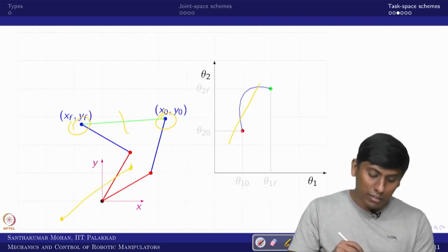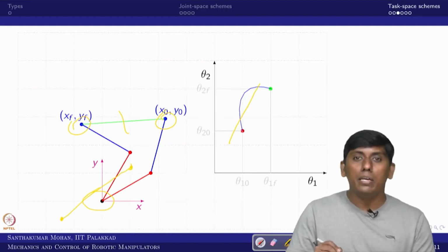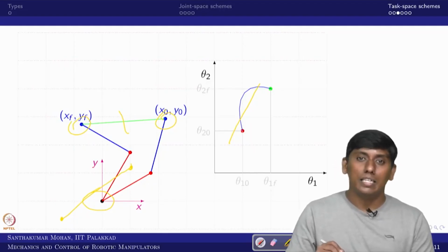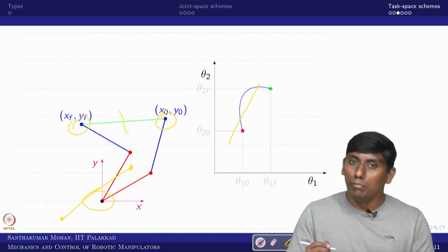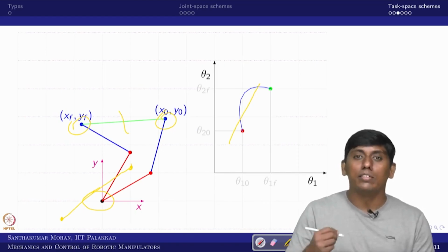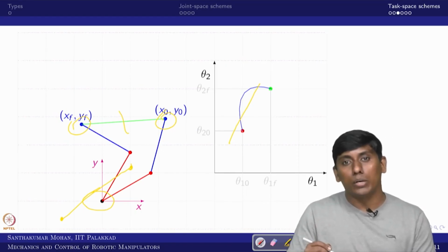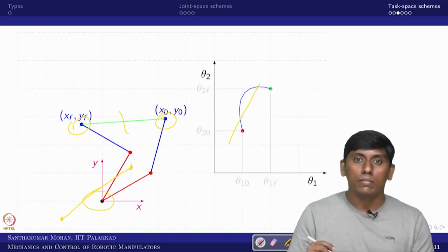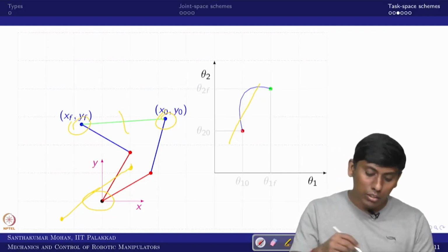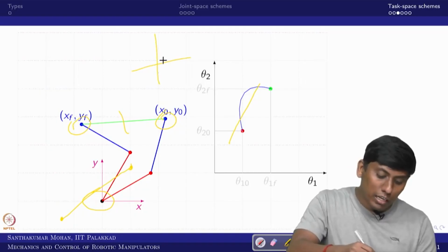I make a straight line. So this zone may be a near singular case. In that sense, the joint acceleration would be infinite. Similarly, joint velocity would be infinite, in the sense infinite joint torque is required to control that, which is not preferred. Similarly, the other way around, you have two situations that can happen.